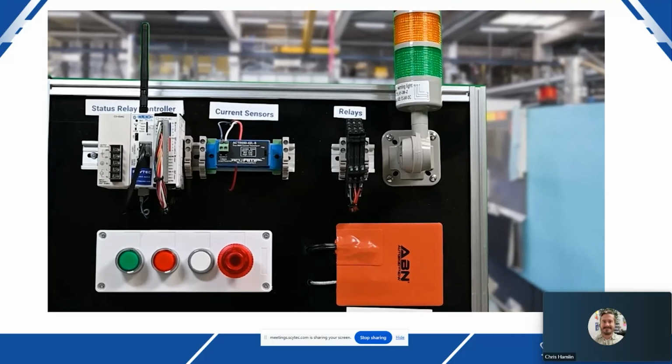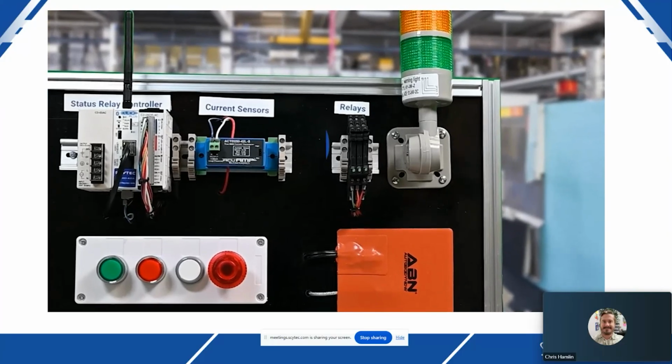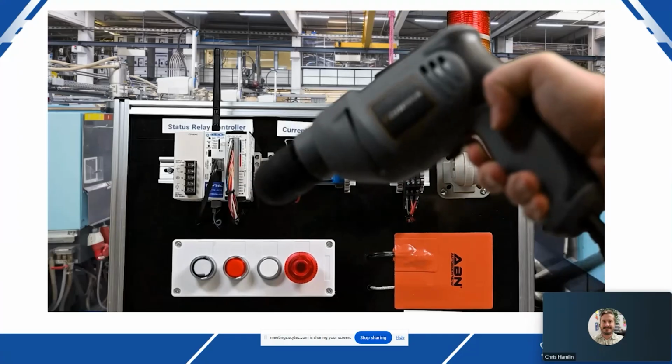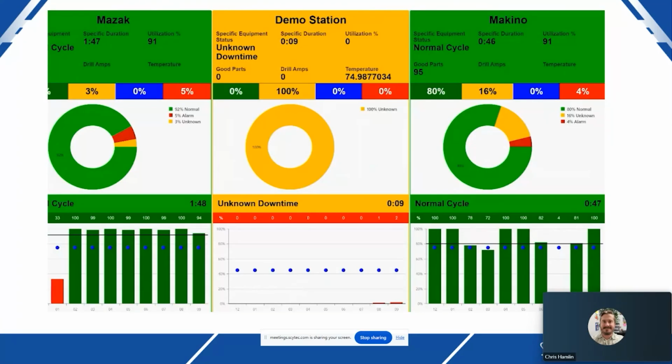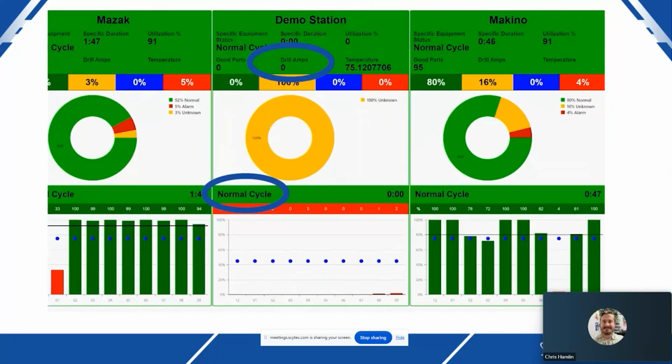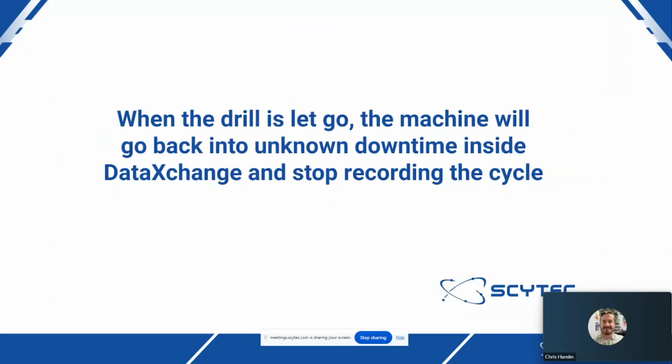So here is our current sensor. This is me engaging the drill, acting as if it were a machine spindle. And then you can see here in one of our real-time dashboards that after pressing that drill, you will see the drill amps increase, and then it's acting like it's going in cycle.